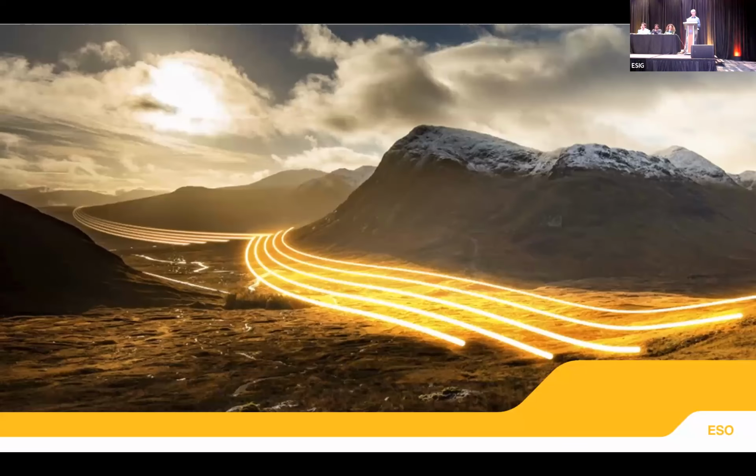So that was all I was going to say this afternoon. So I think the summary is, though, better transparency, knowing where that cliff edge is, really linking together your frequency response with the inertia on the system and making that trade-off for your particular part and your particular system. Do you have a little bit more access to more low carbon inertia, therefore your frequency response doesn't need to be as quick? Or do you not have access to inertia and therefore your frequency response needs to be quicker still? And then you can reduce the amount of inertia you need on the system. So with that, I will leave it there. Thank you very much.